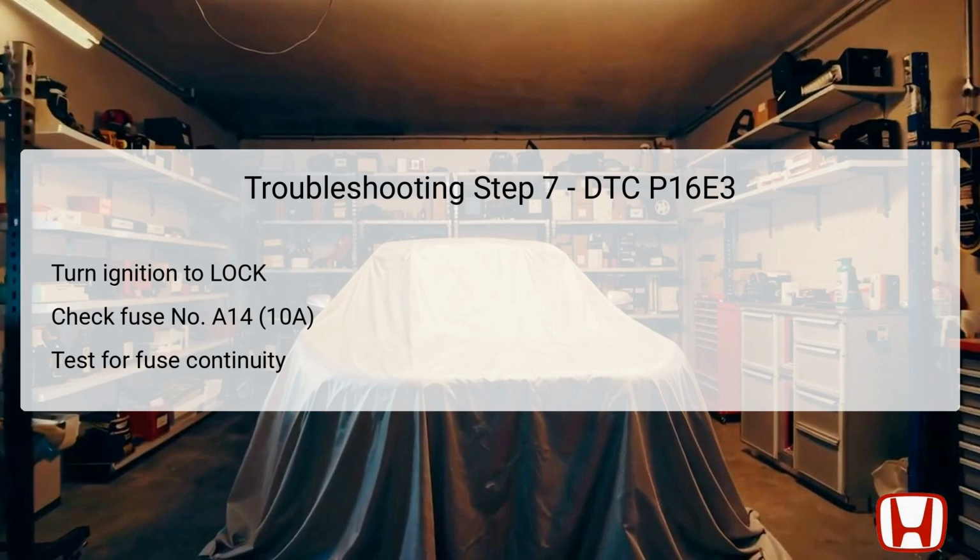If the fuse is good, you can proceed to the next step. However, if the fuse is blown, it indicates a short circuit in the +B horn wire, necessitating repairs and replacing the fuse before further diagnostics.